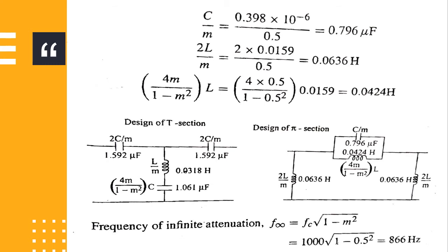So the last parameter, frequency of infinite attenuation, F infinite, is FC into root of 1 minus m square. So here you will get 866 Hertz.